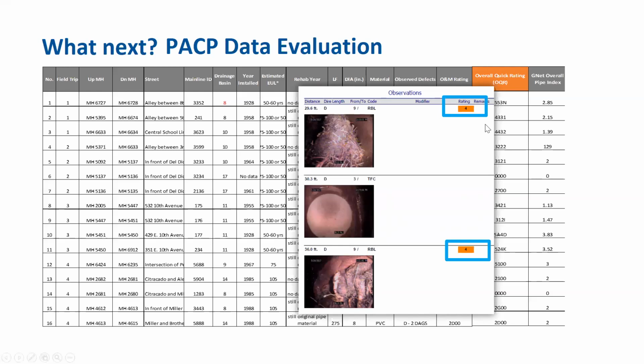Now these condition grades are based on the significance of the defect, right? For example, the extent of damage, whether that crack is longitudinal or maybe just short for a specific segment within the pipe segment, or the percent of restriction to flow capacity, or the amount of wall loss due to deterioration. Pipe thickness just starts decreasing.